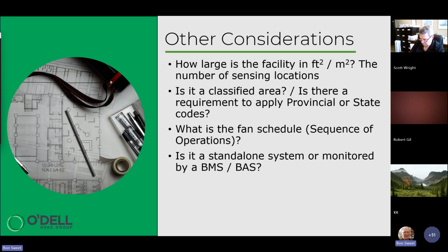It can send a contact closure, which most fire alarm control panels will accept as a supervisory signal, such that when the firemen show up on site, they know where the oxygen is coming from that's feeding that fire.